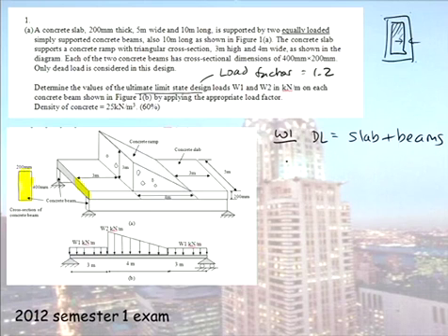So, my slab load is equal to area times density. The cross-sectional area I'm talking about, the whole thing here, is 5 metres wide, so that length in there is 2.5 metres. So it's simply 2.5 times 0.2 times the density of 25. And that gives us a load of 12.5 kilonewton per metre.